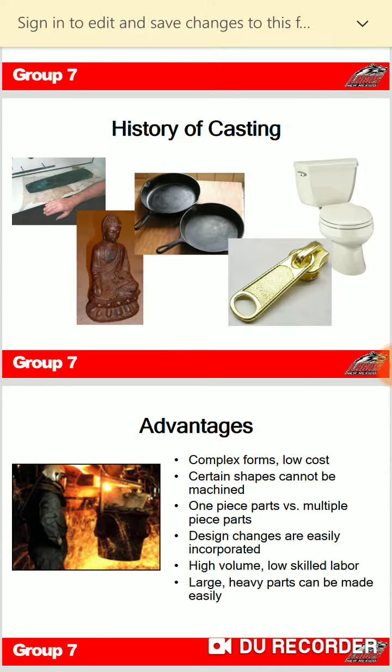In metalworking, metal is heated until it becomes liquid and is then poured into a mold. The mold is a hollow cavity that includes a desired shape, but the mold also includes runners and risers that enable the metal to fill the mold. The mold and then metal are then cooled until the metal solidifies. The solid part is then recovered from the mold. Subsequent operations remove excess material caused by the casting process.